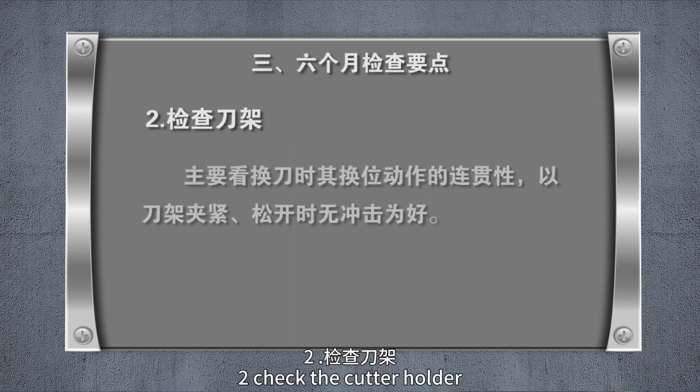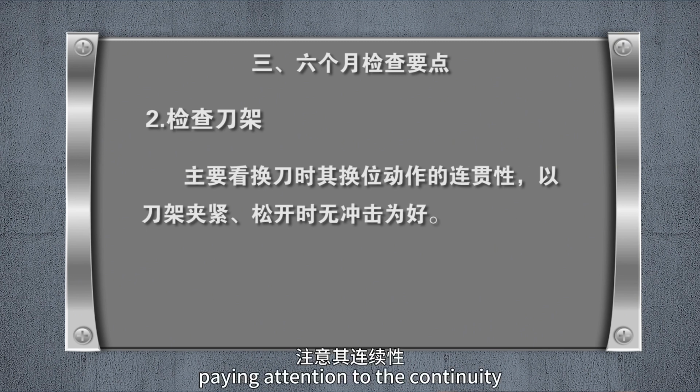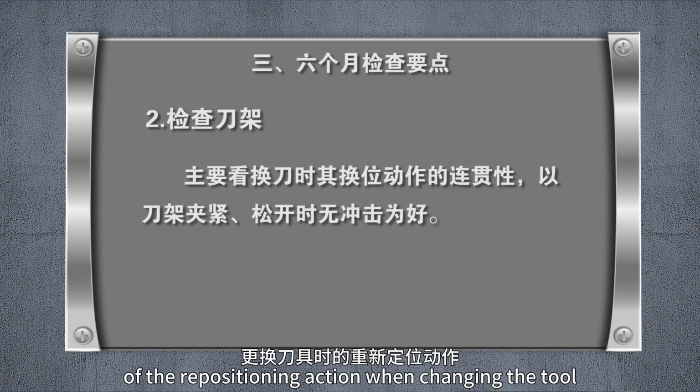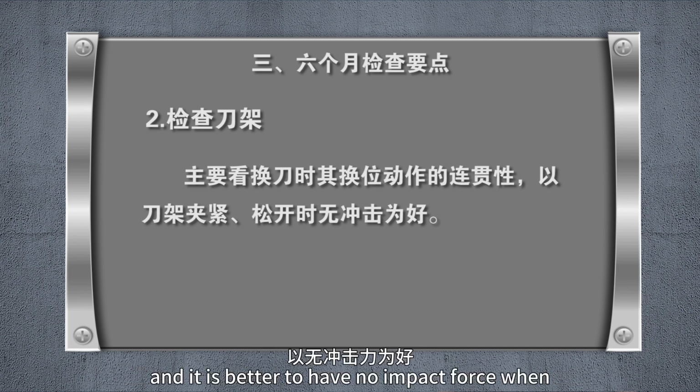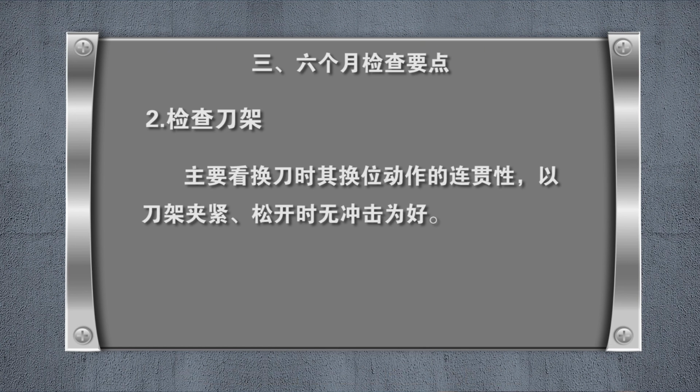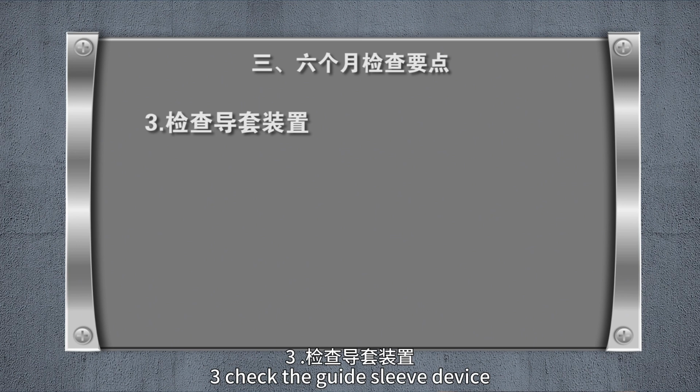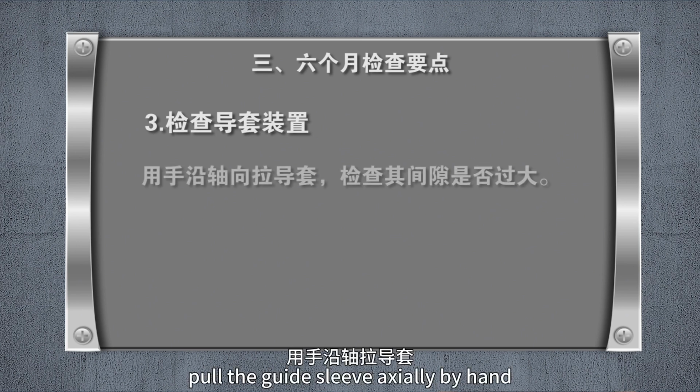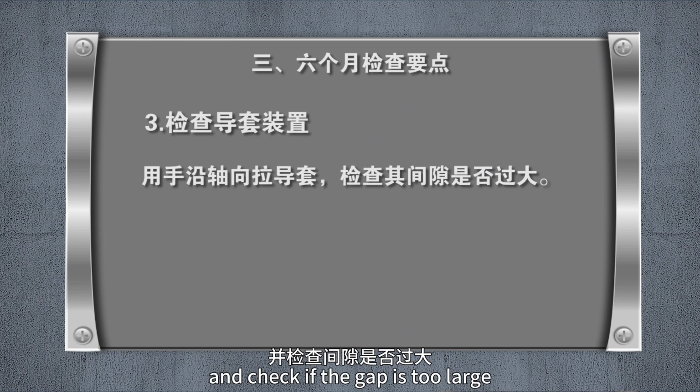2. Check the cutter holder. Pay attention to the continuity of the repositioning action when changing the tool, and it is better to have no impact force when clamping and releasing the tool holder. 3. Check the guide sleeve device. Pull the guide sleeve axially by hand and check if the gap is too large.